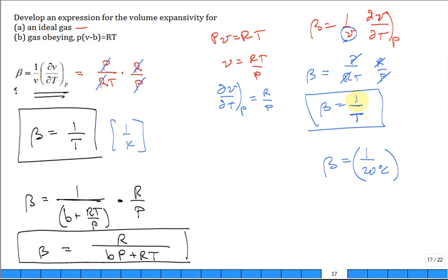Now also, when I teach heat transfer, some people will say, oh, I have liquid water. And liquid water can be hot and cold, and you can get natural convection of liquid water. But I need beta for liquid water. I'll use 1 over T. They forget that this started with ideal gas assumption. This only applies to ideal gas. Now, if you get a different equation of state, you can get a different expression for beta. What about beta for liquid water then? You have to go find it. It'll be listed in a table. Typically, there's not a simple analytic expression for it.